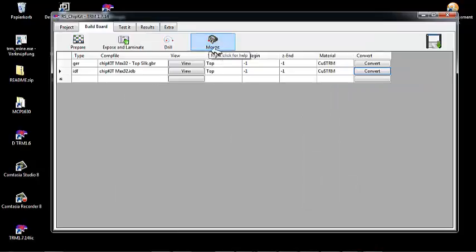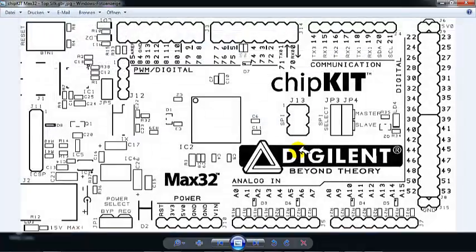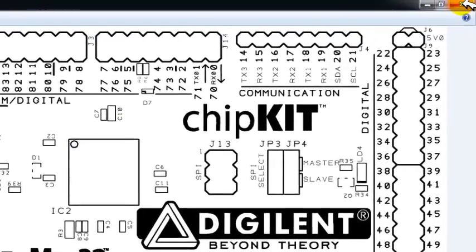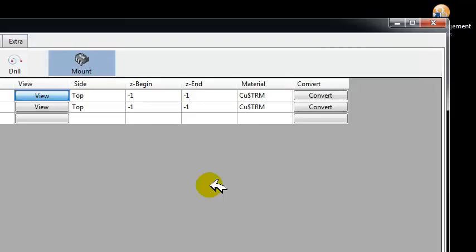Next step is to create components. There are several ways of doing that. For example, we could start interpreting the silkscreen again by importing the Gerber and then using this as a background template to draw components manually. Or we could use the IDF files for component creation.